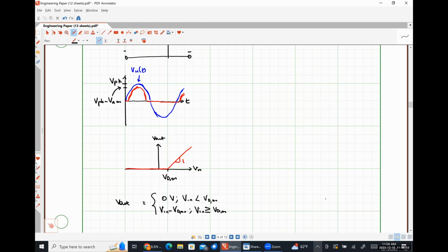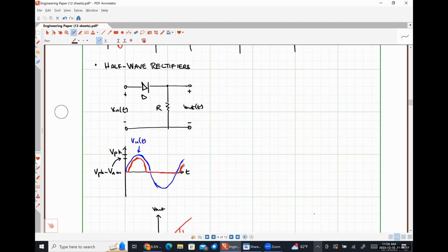On the right-hand side of the page, now we're going to talk about our other half-wave rectifier, which is just a negative half-wave rectifier. What modification do you think I'm going to have to make to my circuit to pass the negative portion of my wave shape? Literally turn the diode around. Absolutely right.